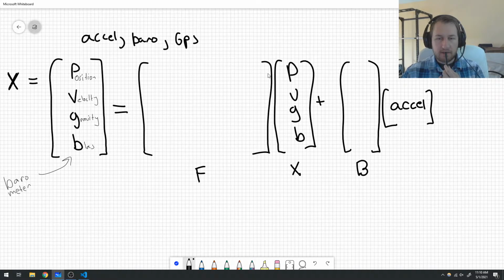They naturally change their bias when the package heats up and stuff. I'm not 100% sure that this tracks that bias too. I think it checks gravity based on the position, velocity, and acceleration, but I'm not sure if it simply looks at the bias or if it's actually trying to detect gravity and it just so happens to be the same thing as your accelerometer bias. So I'm not 100% sure.